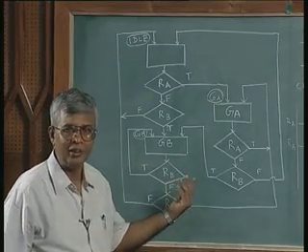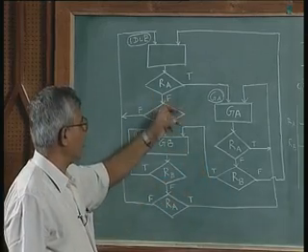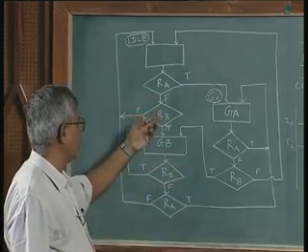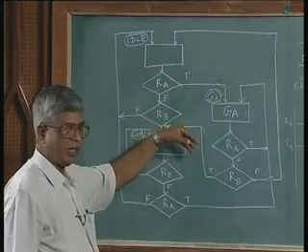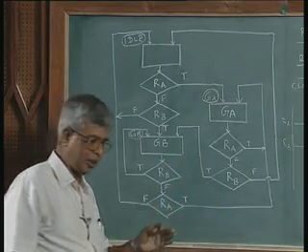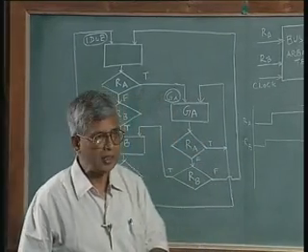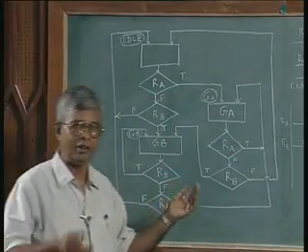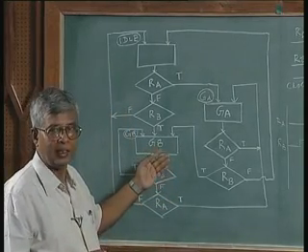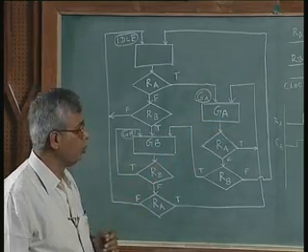As I said, this is nothing but a state graph. You can think of this as a 3-state graph with RA and RB being inputs, GA and GB being outputs, and under different conditions of RA and RB, they go to different states and give different outputs. So we know how to do that, but we will not redraw the ASM as a state graph, because we know how to implement a state graph into hardware. Actually, we said the advantages of ASM: easier, elegance, etc. So we will see how to directly translate or map this ASM into hardware. That is what we will do next. That is implementation of ASM.